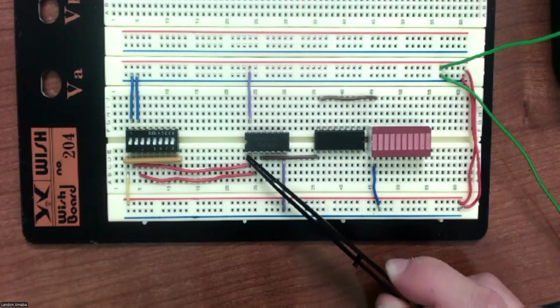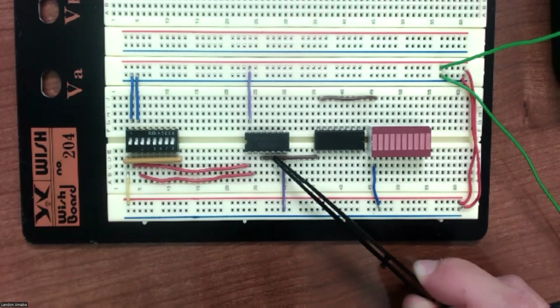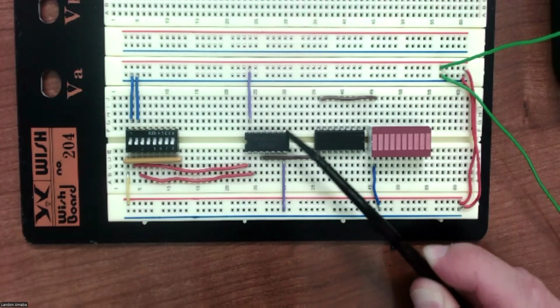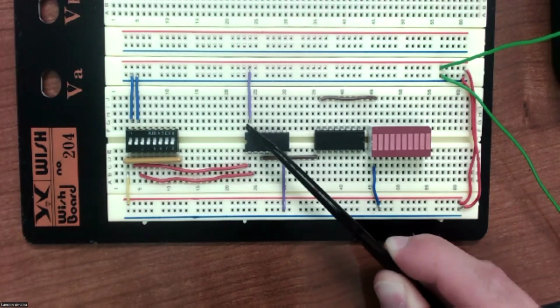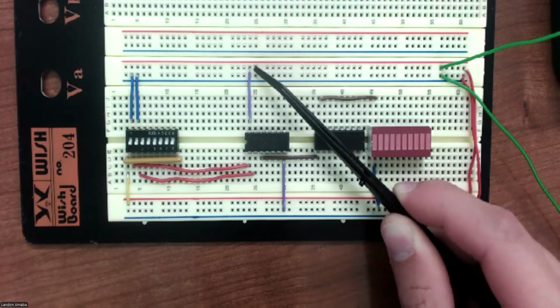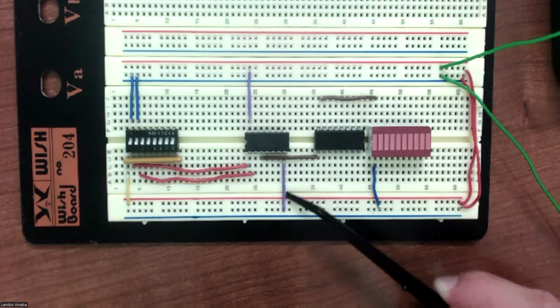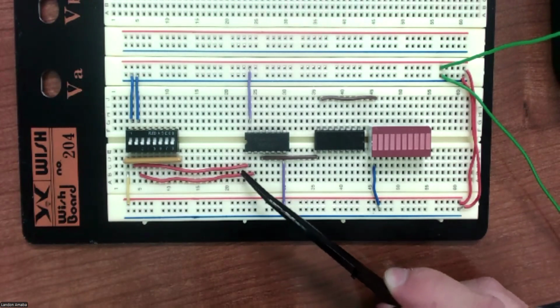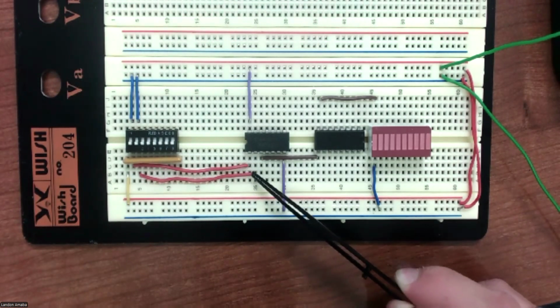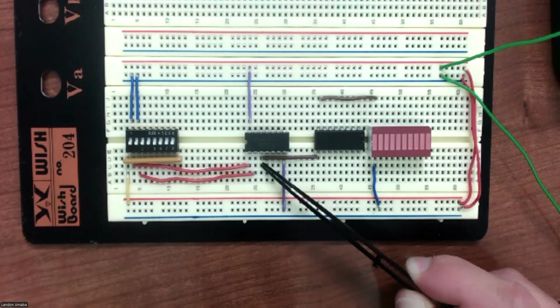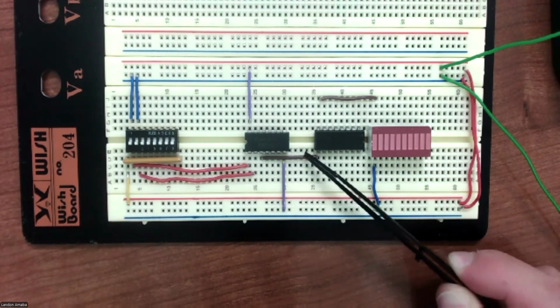When you number these pins, you start here, you work your way down to the right, and you go up and then go back down. So this is power, and then we'll connect this one to ground. And you can see we have our 2 inputs going into these first 2 leads, and the output of the NAND gate coming in from this black wire.